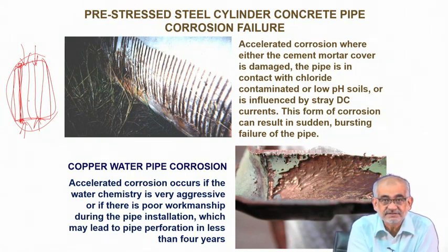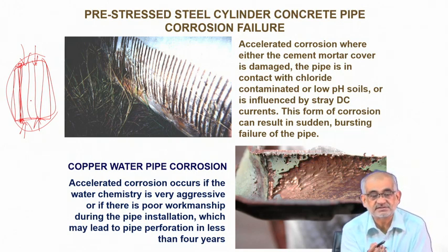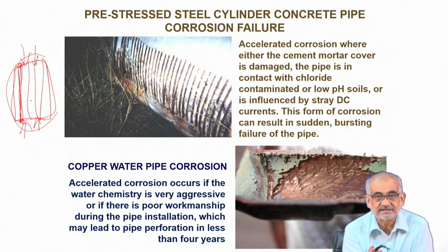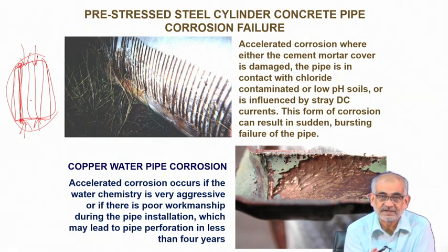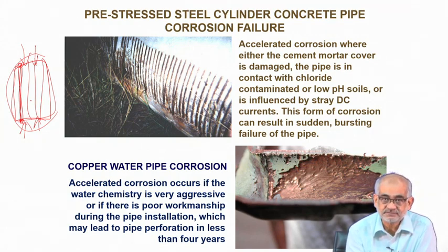But the steel and concrete interface is always a very probable spot for corrosion or damage to occur, because you are crossing over, there will be some amount of gap, and that gap, obviously for the structures you can't see from the outside, but the length scale of such an air gap could be of the order of a few micrometers or even less. Nevertheless, this is also the region where you expect some moisture to be trapped, because for setting the concrete you add water all the time.